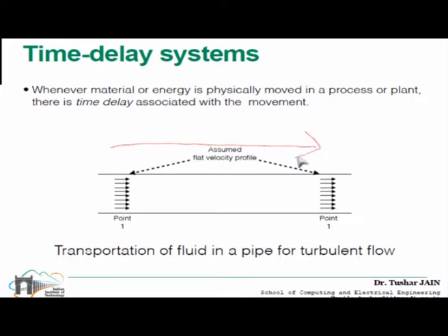As you can also see in this slide, the liquid is flowing from one point to another, and of course it will take some time. This is what you call the transportation lag or the transportation delay. So we will see how you model this and what the effects of this time delay are.